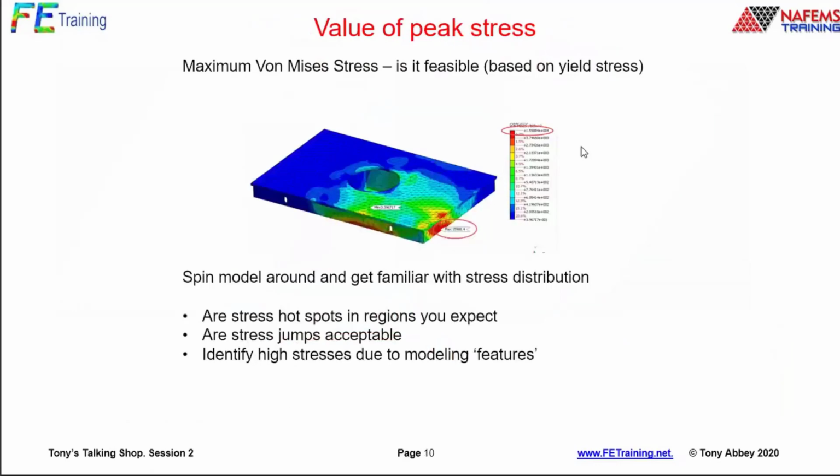Now let's look at stresses. And again, the idea is thinking of this manager's check. Basically, I'm going to look at the maximum stress, and I might as well look at von Mises stress because that's pulling everything together. Later on, I'm going to look at component stresses, maximum principal stresses, and so on. But at this point, I just want to get a snapshot of where that maximum stress is.